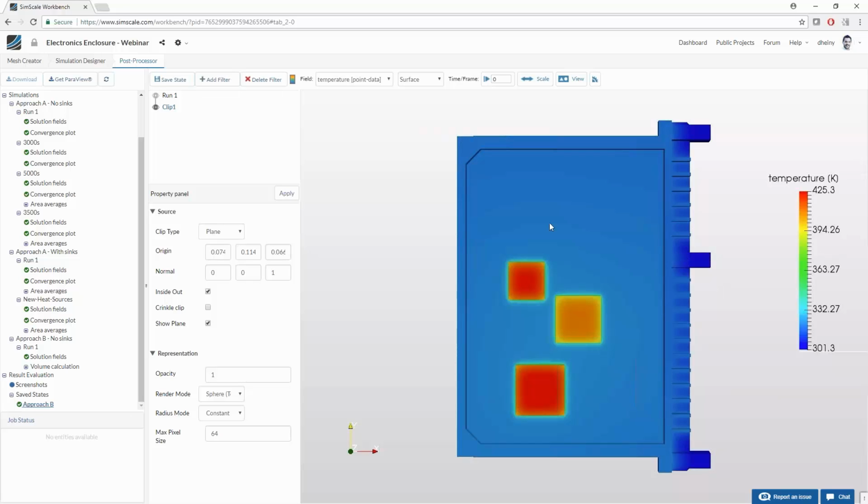of my conductive analysis, right? So I can see chip 1, chip 2, chip 3. Chip 1 looks like the hottest, somewhere at 425, 427 Kelvin, which, we're going to discuss that in a second, is significantly too high, right? Most chips go up to 90 degrees Celsius and maybe have peak loads that they can survive, but in our design scenario, we're shooting for less than 90 degrees Celsius, or roughly 370 Kelvin. So we're seeing this is too high.